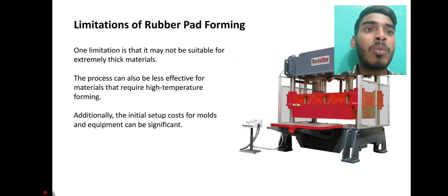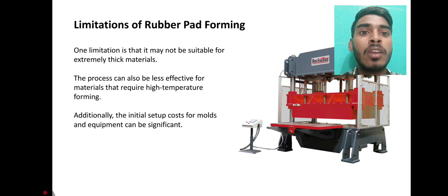Limitations of rubber pad forming. One limitation is that it may not be suitable for extremely thick materials. The process can also be less effective for materials that require high temperature forming. Additionally, the initial setup cost for molds and equipment can be significant.